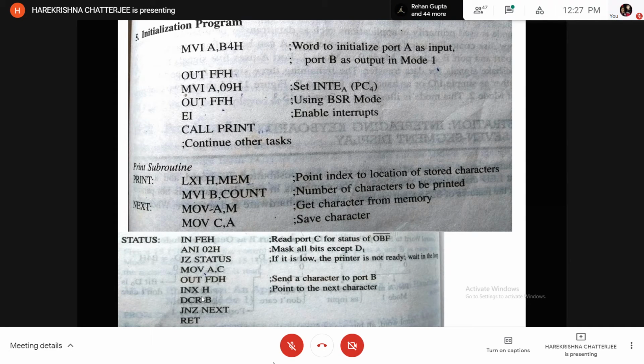to hold the source data for some time to be read by the receiver, and generates the appropriate buffer full signals. Based on that, the source and receiver will be reading or sending the next data byte. If the buffer is empty, then the source can send the next byte. And if the buffer is full, then the receiver can read the byte from the buffer. So that has been done. So, out to the port B register.